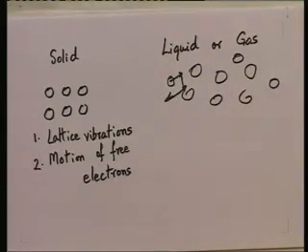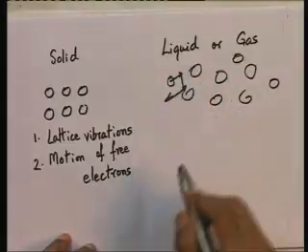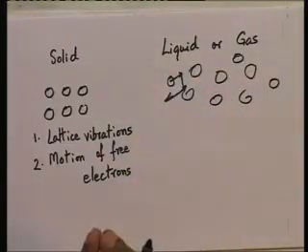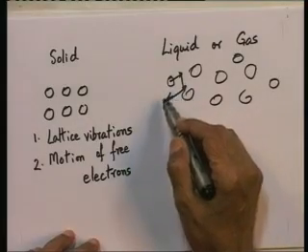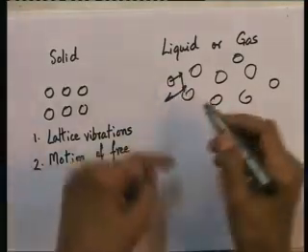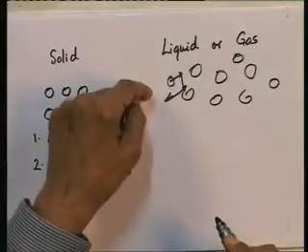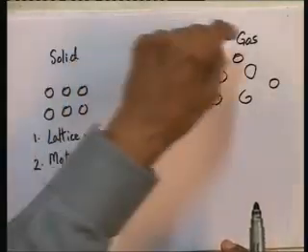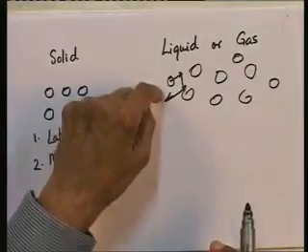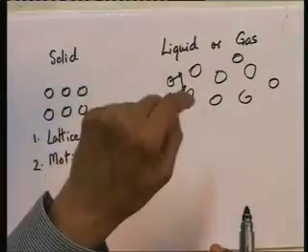Now, in an overall sense, the liquid or gas may be stationary. In a macroscopic sense, the liquid or gas may be stationary. But in a stationary liquid or gas, there is always this random motion taking place over short distances. In a gas, those distances are a little longer, in a liquid, those distances are a little smaller. All right. Now, the transfer of energy which occurs due to collision between molecules when they move in this random fashion over short distances within a liquid or a gas is what we call conduction in a liquid or a gas.